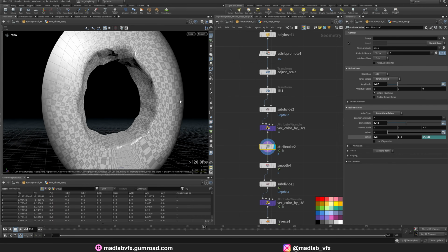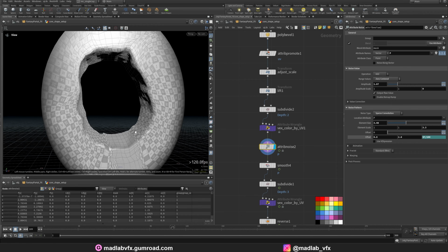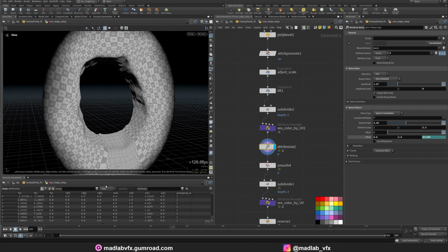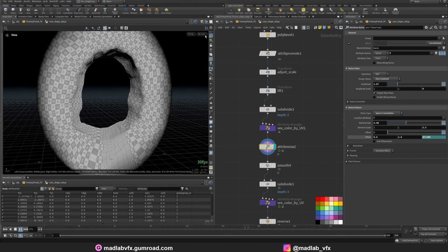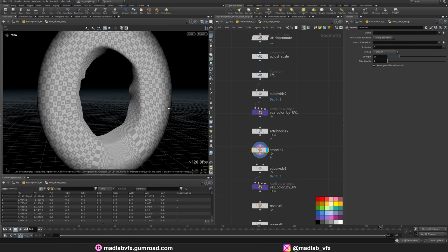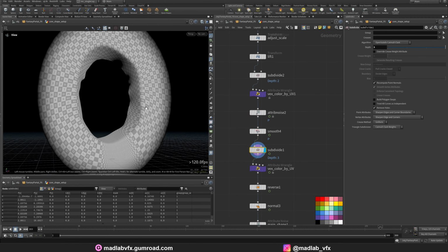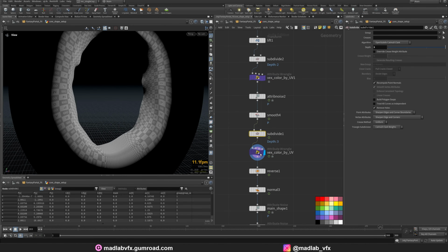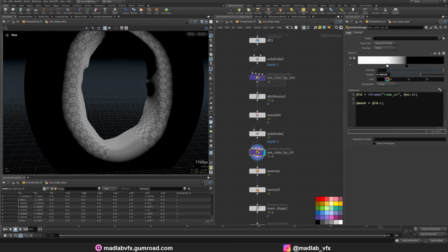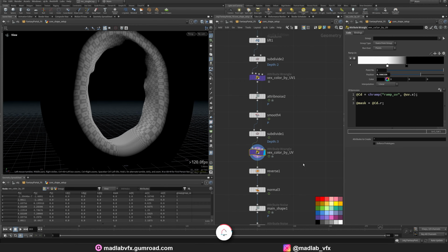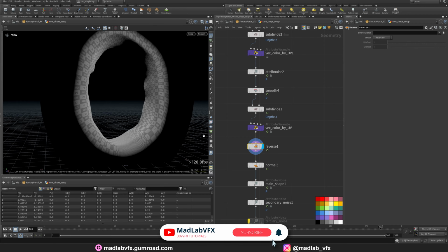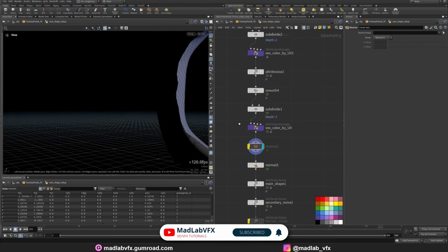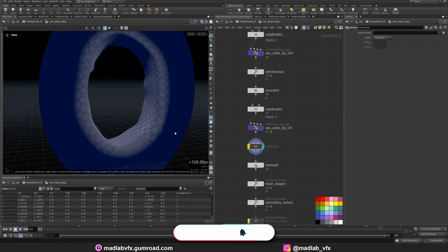I implement some noise. Let's disable the specular here. The first pass of noise. Then I smooth this noise a little bit, subdivide again 3 more times to create a higher resolution geometry. And I use the same Vex script node, just to change the gradient ramp here. I reverse that because the polygons are from the back face.